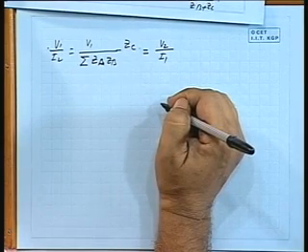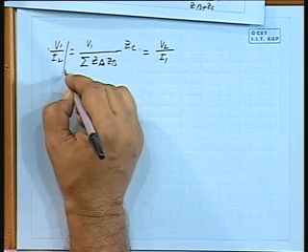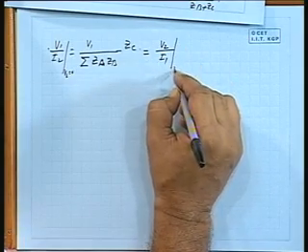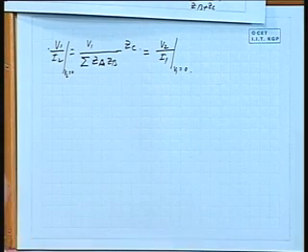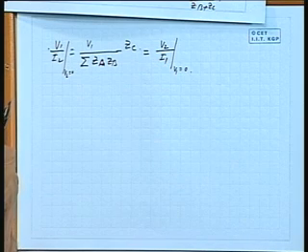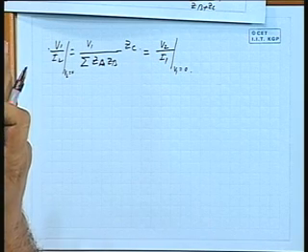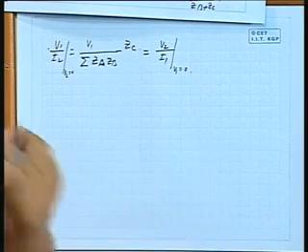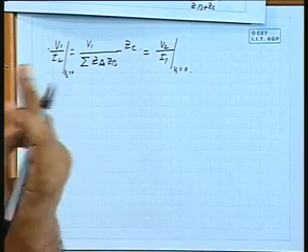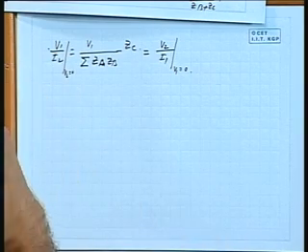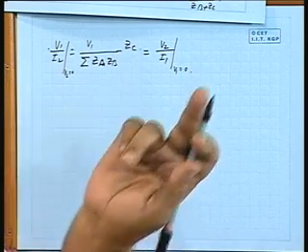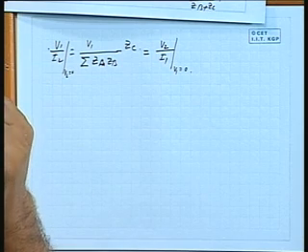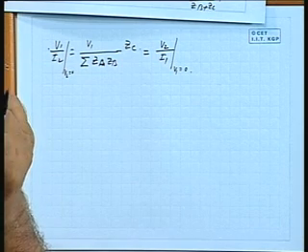V1 by I2 when V2 is shorted, and V2 by I1 when V1 is shorted. That means in any multi-port network, if I inject a voltage at one terminal pair and short circuit any other port pairs and measure the current there, then the voltage current ratio is the same if I interchange the source and the shorting terminals.